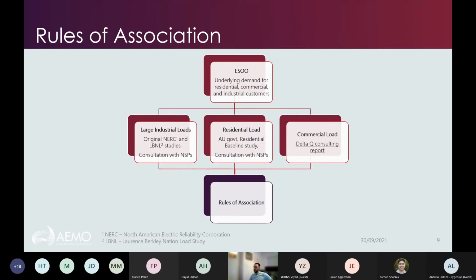I haven't checked it in a few months, but those EVs are say 60 kilowatt hours to 150 kilowatt hours, whereas a typical house might be 30 kilowatt hours per day. And you can imagine an EV being used to travel around the city all day, come home, plug in to charge, and you've got the equivalent of 5 houses consuming power at that one residence. So you can imagine the sort of end-use load mix change, and why we have to build battery models on top of load models, on top of distributed PV models, on top of the other models that we have.